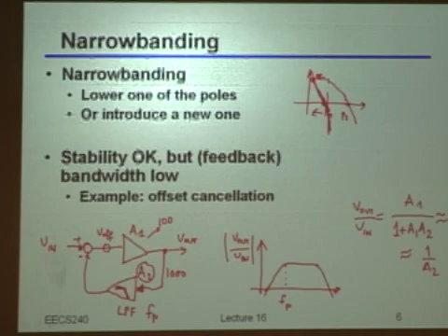If you could push it as much as you can, you would go for it, since you want to null the DC component, right? Any idea? So you want 1 over A2 to be almost 0 at DC. So you're really looking potentially for a component that has infinite gain at DC. So an integrator, for instance.